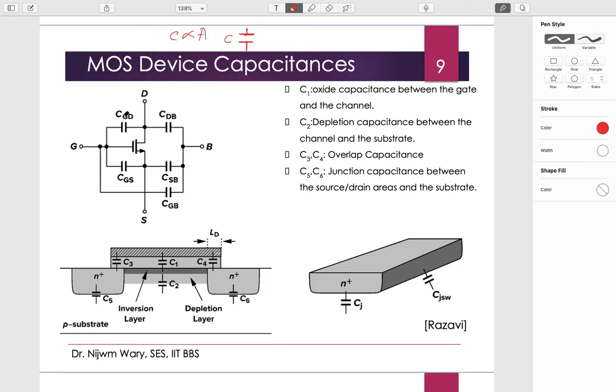Of course it's also dependent on the distance. So if I reduce the size of the MOSFET as small as possible, the parasitics associated with this transistor also reduce. That's why it is possible to go for very high speed operation. If I have to design a very high speed processor, all my individual MOSFETs should be of very high speed.